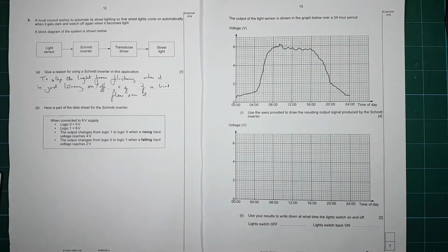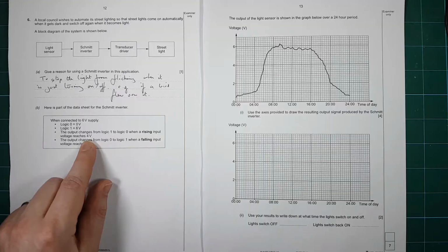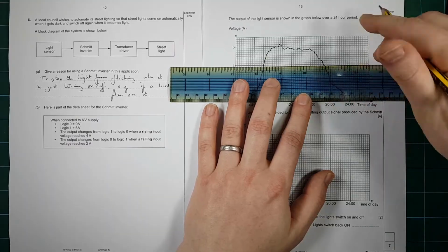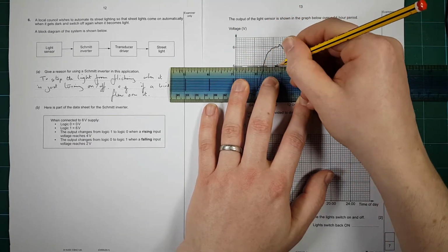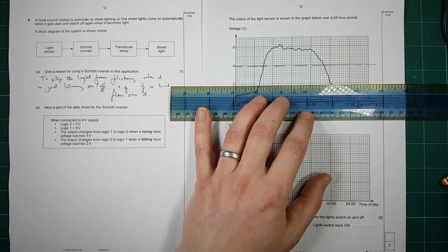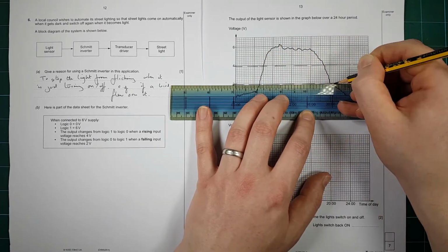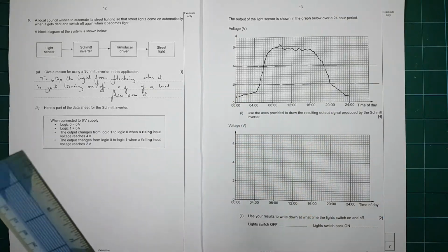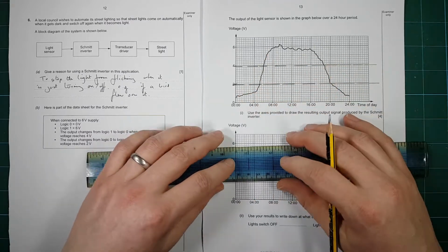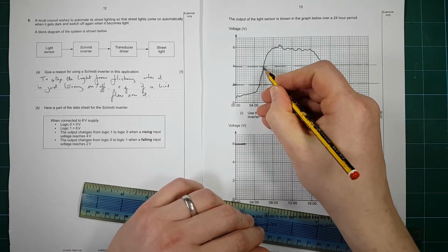So now we need to work out when it does everything. So the first thing we should do is draw in these values. So at 4 volts and 2 volts. So get 4 volts here, and we just draw a dotted line across there, and 2 volts. Okay, so those are the thresholds then. So it's going to start high because this starts on very low. Now what you have to do is just be careful. Does it change here or does it change here?